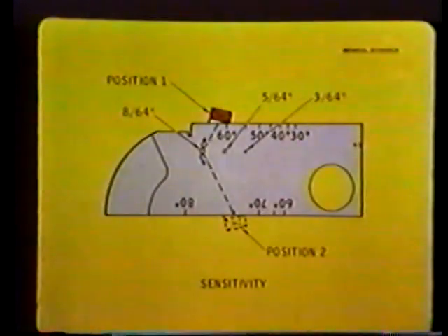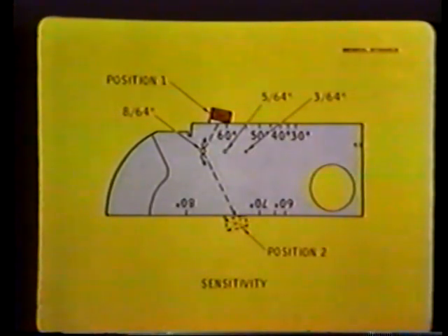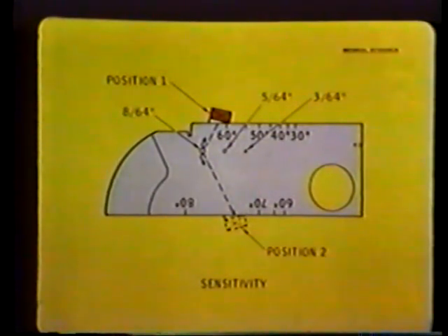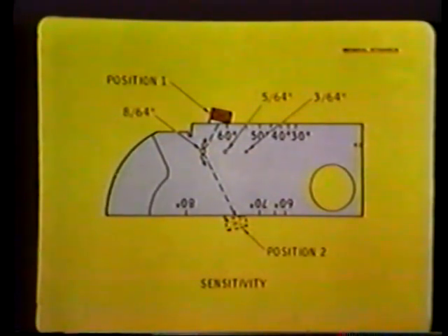To check instrument and transducer sensitivity, the transducer is first coupled to the notched side of the block and moved about till a peak signal is obtained from the desired hole. Instrument gain or sensitivity is set to the desired amplitude. The transducer is then moved to the opposite side of the block to provide a greater travel distance, and the amplitude of the hole reflections compared.